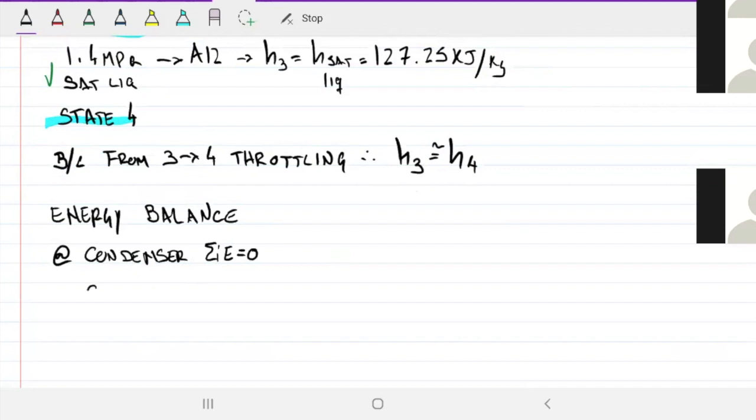In other words, all the energy that the water absorbs has to be equal to the energy being released by the system. I can do this with either energy or power. In our case, power is more useful. This is what we were talking about just before when finding the energy of the water. There are two ways you can go about it: you can grab enthalpies from the table, or you can use CP.